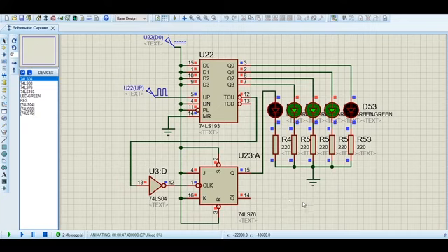With those configurations, this counter will just count according to the natural 4-bit counting and then trigger this JK flip-flop configured as a T flip-flop when one full counting cycle from 0 to 15 occurs. With that, the counting of all the 5 bits put together will just go from 0 to 31 continuously, as shown on these outputs.